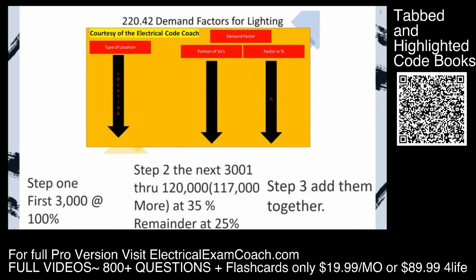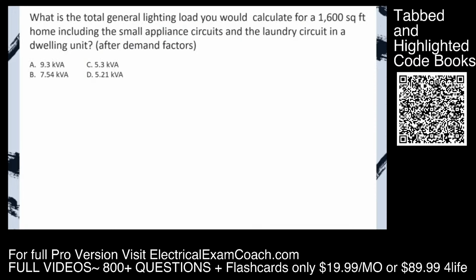Then we're going to take that new reduced load, add those two together, and that's going to give us our total load. What is the total general lighting load you would calculate for a 1,600 square foot home, including the small appliance circuits and the laundry circuit in a dwelling unit after demand factors? I want to note that on your examination, they will not mention the small appliance and the laundry circuits. You just have to know that anytime you're doing the total general load or you're doing a whole house load calc, you have to tack on that 4,500 VAs.